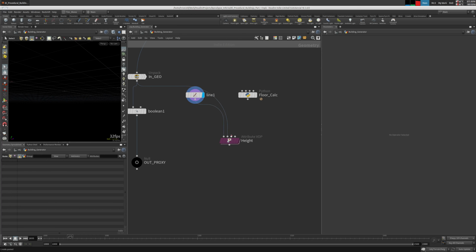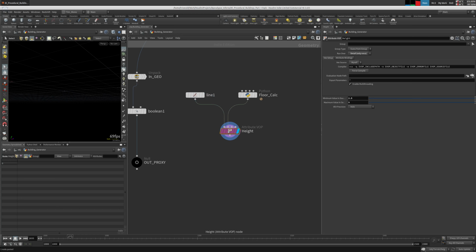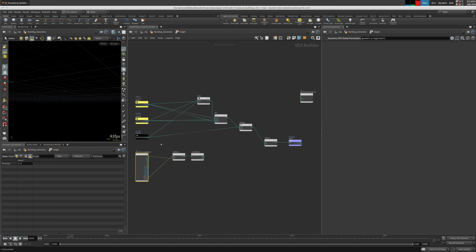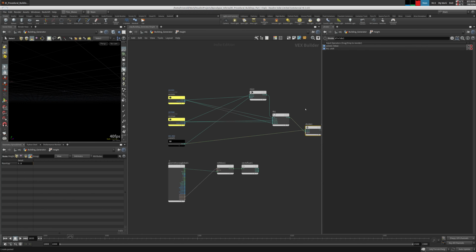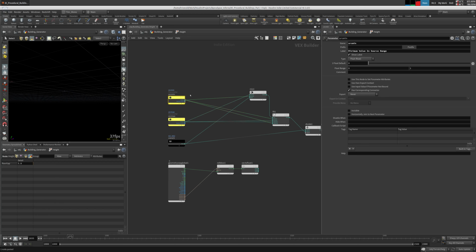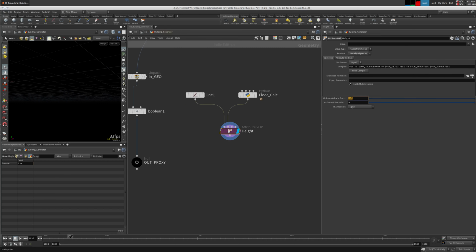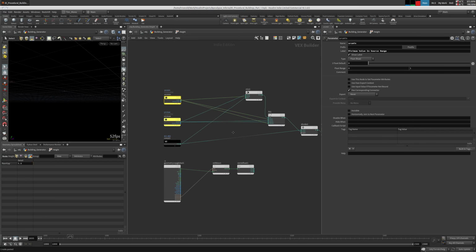Okay, delete. You go there. This doesn't even do anything, to be honest. I think it outputs a value called floor gap, and it's 5 based on the height of the building divided by a minimum value and a maximum value, which is 2.5 to 5. So the minimum value of the floor heights can be 2.5. The maximum value of the floor heights can be 5 meters.